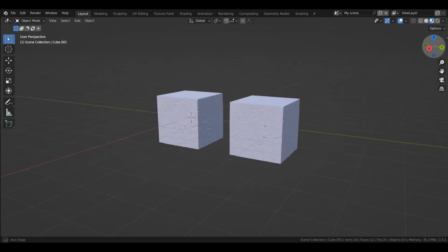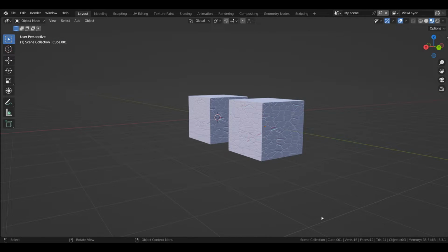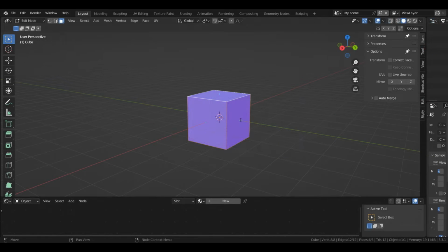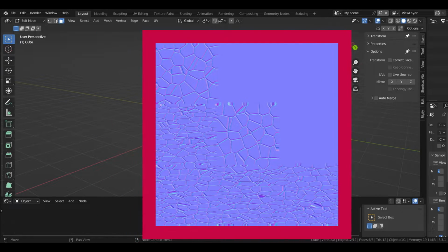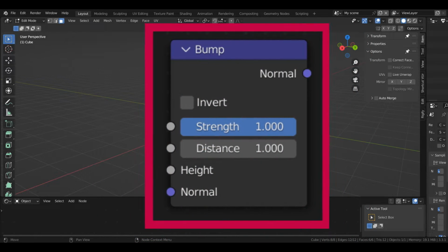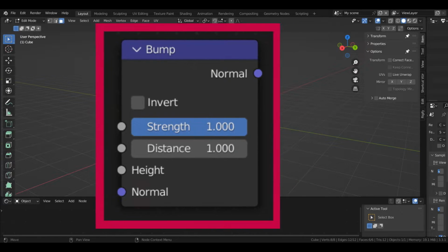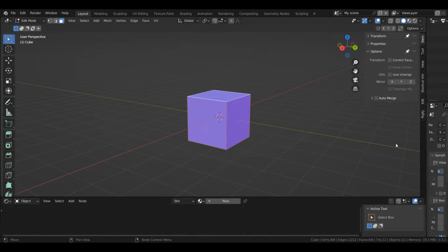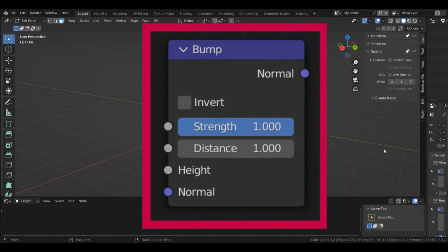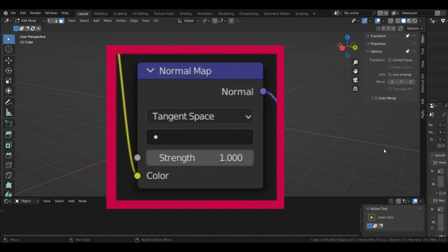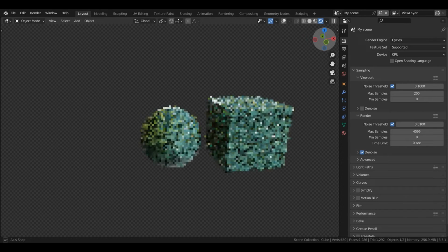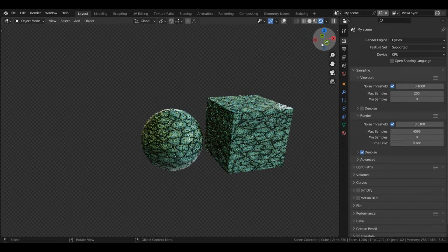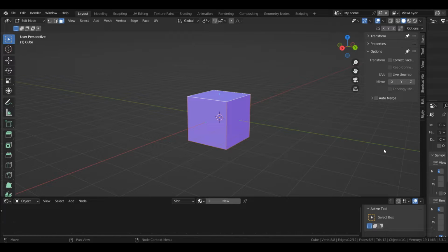I like to think of a normal as being able to be deformed like Play-Doh into a unique detailed normal, and to control this deformation we can use a normal map or some sort of normal input. For example, this bump node, essentially what's happening is it's translating bump info into normal information. We will cover bump in greater detail in the next episode. What makes normal information even more amazing, whether that's through using a bump node or a normal map node, is that the altered normal will react to light and material changes, just like a modeled geometry, even though this face is just 4 vertices.